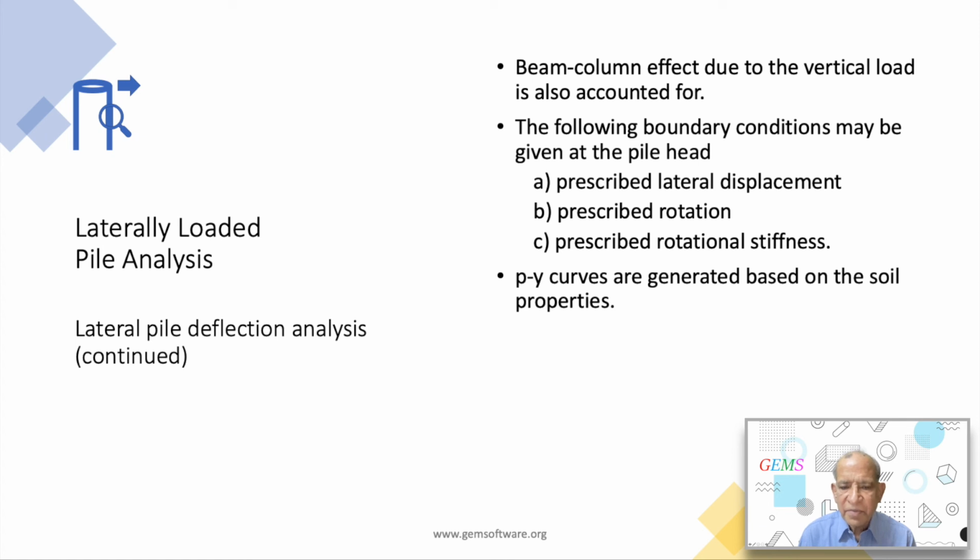The results are presented in two parts. The first part consists of a set of PY curves for each layer under static loading conditions, and a set of PY curves for each layer under cyclic loading conditions. For each loading case, the second part results consist of lateral deflection and slope diagrams, shear force and bending moment diagrams, and soil pressure diagram.